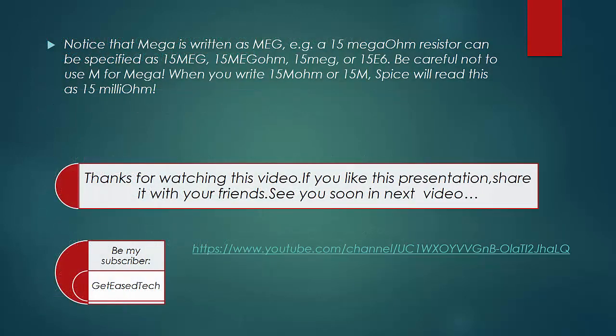There is another note for you guys. Notice that mega is written as meg. For example, a 15 mega ohm resistor can be specified as 15 meg, or 15 meg ohm, or 15e6. Be careful not to use m for mega. When you write 15 m ohm or 15 m, SPICE will read this as 15 milliohm. I am warning you guys again and again. Please be careful about this.